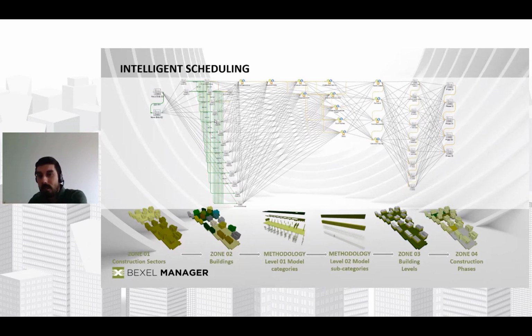And then with this smart software, we're going to be able to reuse this methodology and scale up the schedule. So with almost the same effort, we're going to create a schedule that is 20 times bigger. That's the whole point: once you define the methodology, the sequence of work, something that is standardized, something that is tied to your classification system, after that you just transfer it to the next project. And on the next project, you're just changing the spatial organization of your schedule because you have projects of a different scale. Of course, you're not going to have the same methodology for a steel structure and a reinforced concrete structure, but between two reinforced concrete structures, you can reuse these methodologies.